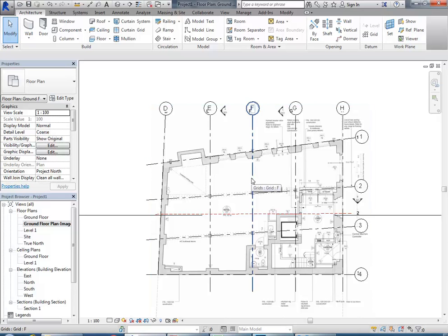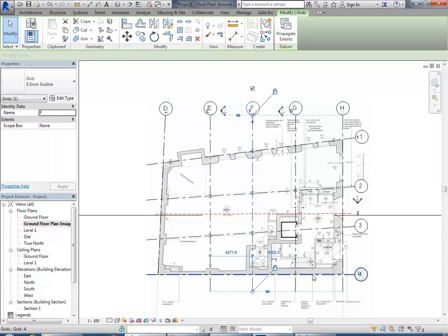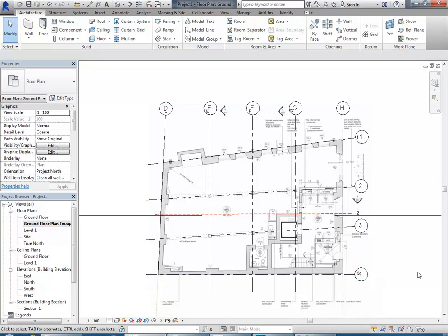And then it'll make things easier with Revit if they're vertical. So don't do them at a slight angle if you don't have to. If you can keep it at 90 degrees. And the same, like I said, with number 4, if you can keep that horizontal, that makes it much better with Revit, just because of the way Revit works. Things that are at a slight angle, if something's 0.38 of a degree off an even degree, it will create all sorts of problems. It'll give you errors constantly.